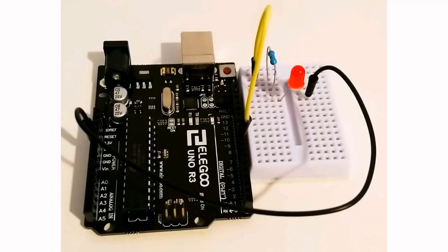And basically here is the wiring diagram for this schematic here. Here is a picture of the actual setup. As you can see, there's the red LED. It doesn't have to be red, it could be any color of your choice. There's the 220 ohm resistor, and it's connected to pin 8 of the Arduino Uno, and this black wire here connects to ground of the Arduino Uno.